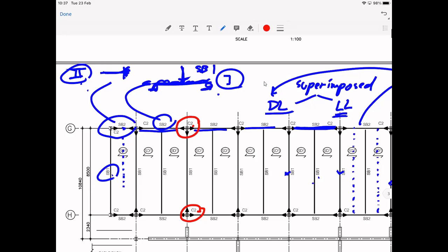Ladies and gentlemen, I am not asking you to design like 2 sides, because this one may be different from that. So after the load summation, you can just use the most critical one, which is this, because the tributary area is this. Therefore, just design this column.